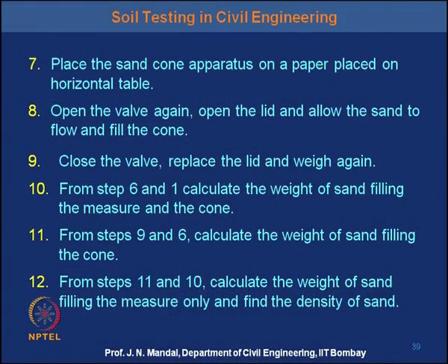Then place the sand cone apparatus on a paper placed on the horizontal table. Open the valve again, open the lid and allow the sand to flow and fill the cone. Close the valve, replace the lid and weigh again. From steps 6 and 1, you calculate the weight of the sand filling the measure and the cone.